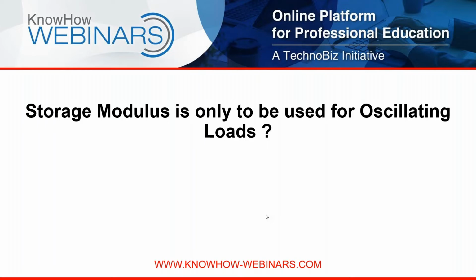Storage modulus is only to be used for oscillating loads. By oscillating loads, you might mean cyclic loads. Yes. When you carry out a viscoelastic deformation in the time domain, there is no storage modulus or loss modulus that is output. The storage modulus, the loss modulus, and tan delta are properties which are output from a frequency test or from a cyclic test.